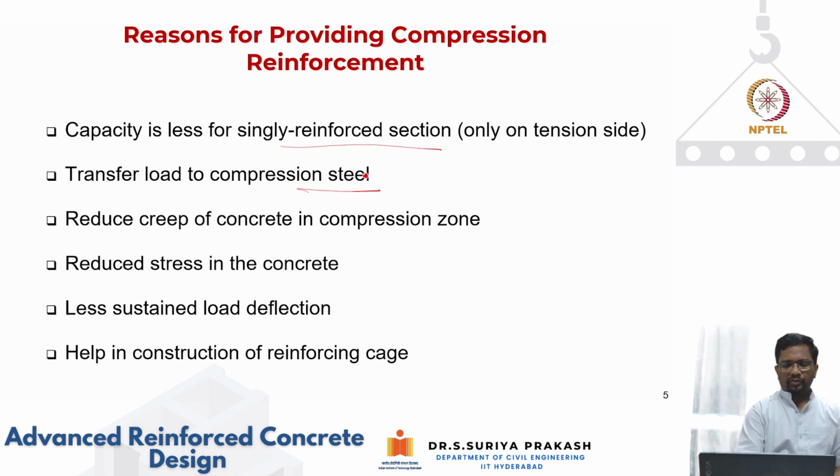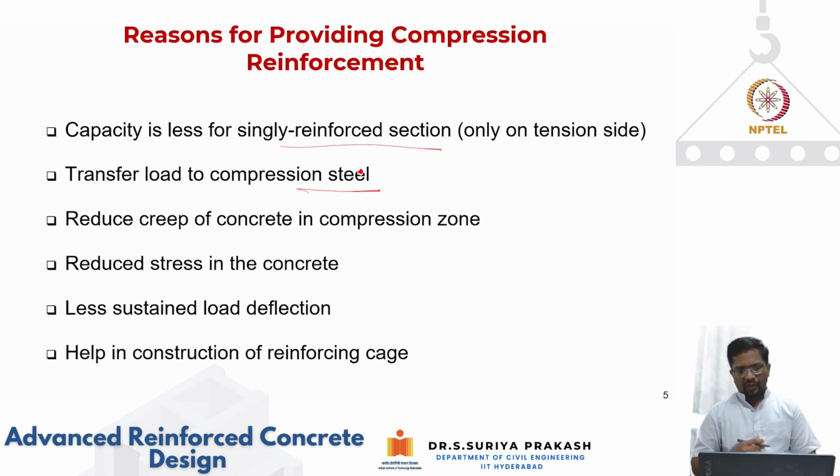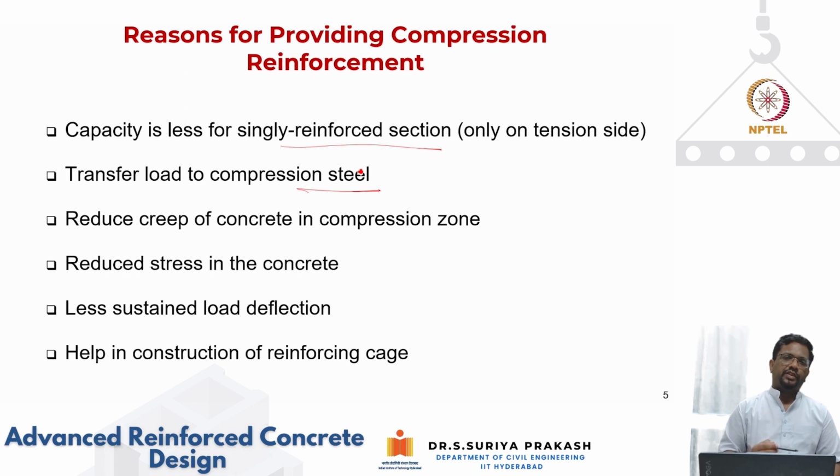Sometimes we also want to reduce the level of stress in the concrete on the compression side, relieve the concrete from taking more stress and transfer the load to the compression steel. So for that reason, from a service level stress analysis point of view, sometimes we would want to put steel on the compression side. More importantly, putting steel on the compression side is going to help in reducing the creep of concrete.